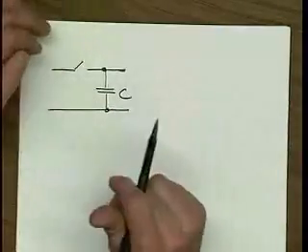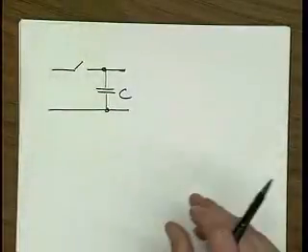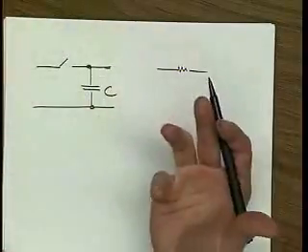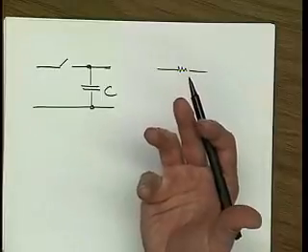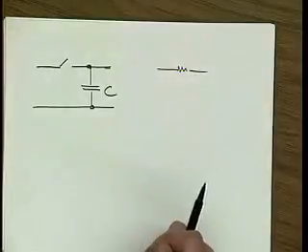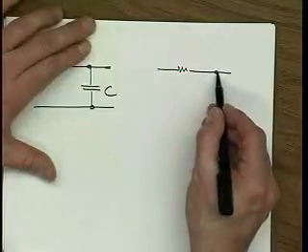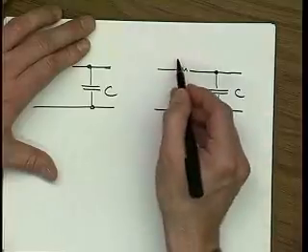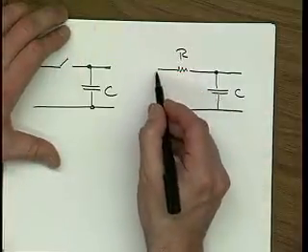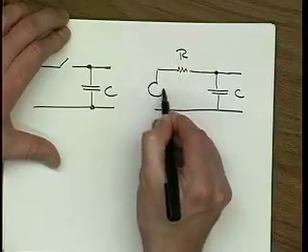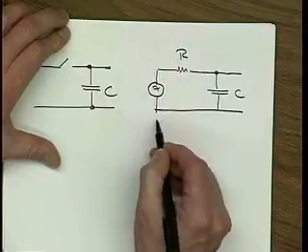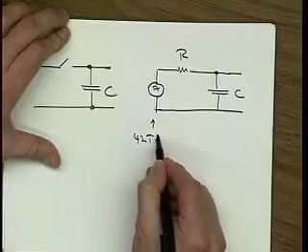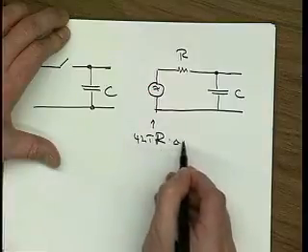Now, what's the switch? Well, in the off state, it presumably is infinitely large resistance. In the on state, it's just a resistor. Right? Most of the time, these switches are made out of MOS transistors. They operate in the diode region where they use the switches. So they're really a resistor. So the situation we really have is a capacitor, and there is a resistor here. And of course, the resistor has noise, and we know what the noise of the resistor is. This is a reasonable MOSFET. It's going to be 4kTR times delta F, right?